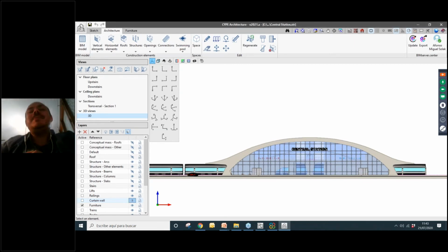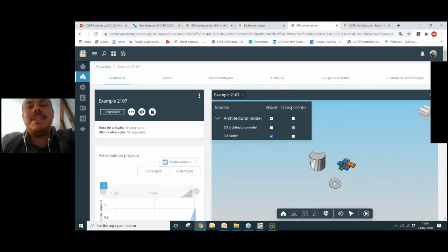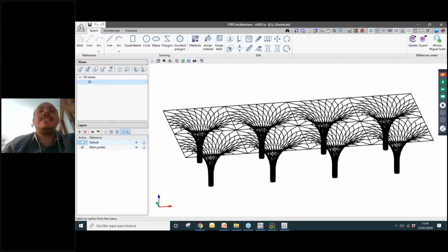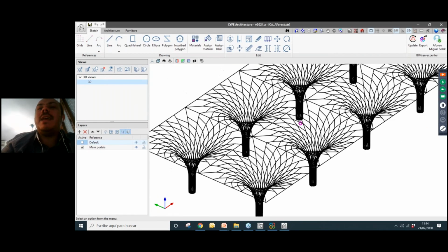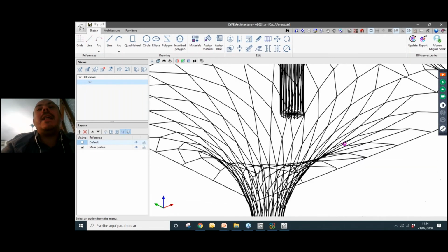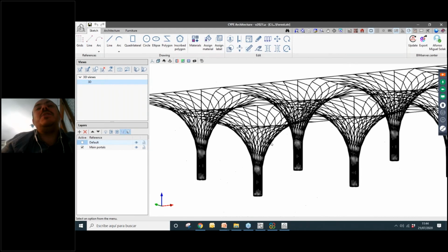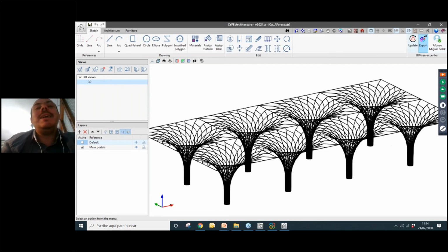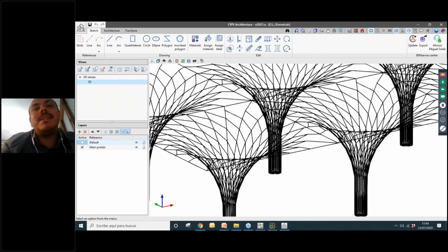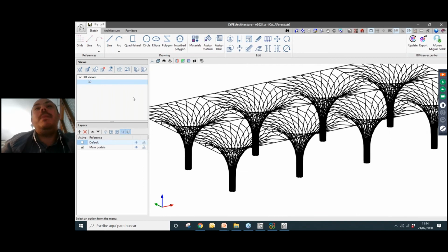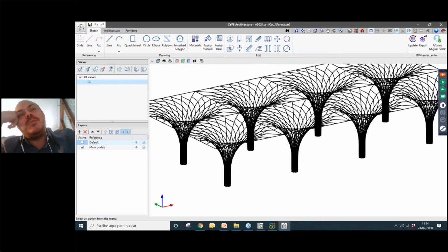So actually, this is part of the presentation of tomorrow, but I will open here just to have a look at this model. It was created just using the sketch tab. So we can create this kind of geometries here. They are just lines. Actually, we don't have the surfaces. The surfaces were erased, and it's quite nice because here on CYPE Architecture they are just lines. Actually, here in architecture we don't have anything. But when we export it to BIM Service Center, then we can characterize these bars, these little lines, as bars on CYPE 3D and generate the structure of this building, or this element. But I will show that tomorrow when we do this workflow.